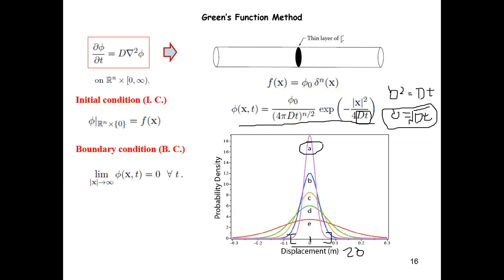And you see clearly that this distance is manifested in our problem, because how far the carbon atoms can penetrate into both sides of this metal bar is basically due to diffusivity, right? So that penetration distance or penetration width is going to be proportional to this quantity, which is basically square root of Dt. Does that make sense to everyone?